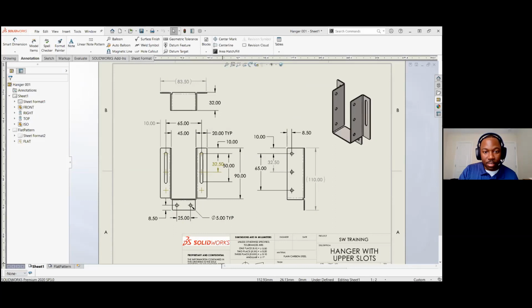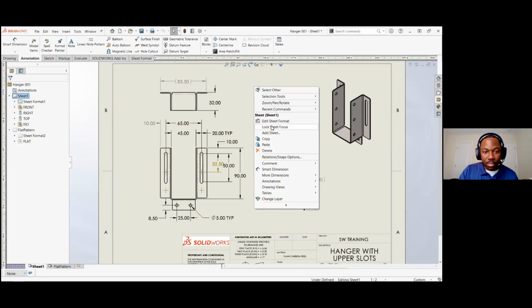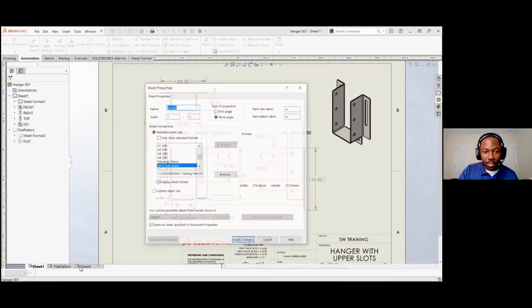I was going to respond to the one about how I'd like to rewrite my variables such as quantity and description in a part and have custom properties that are always filled in automatically, asking about a webinar. What I usually do is point people to add the custom properties to the part and assembly templates. That way when you go file new, the description is already there, or the weight is already there. The weight could be pointing at the mass properties. Description could be blank, or sometimes I have it XXXXXX just to draw attention to it once it shows up in the bill of material. So that might be a good way to do it.